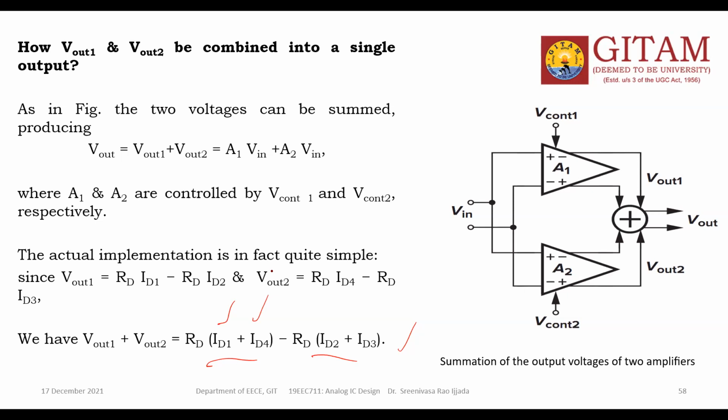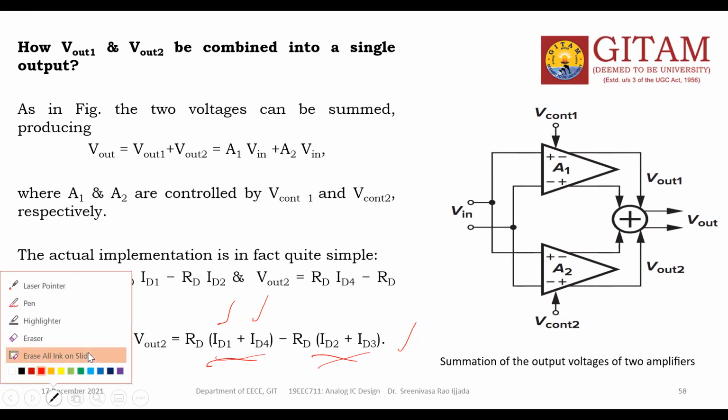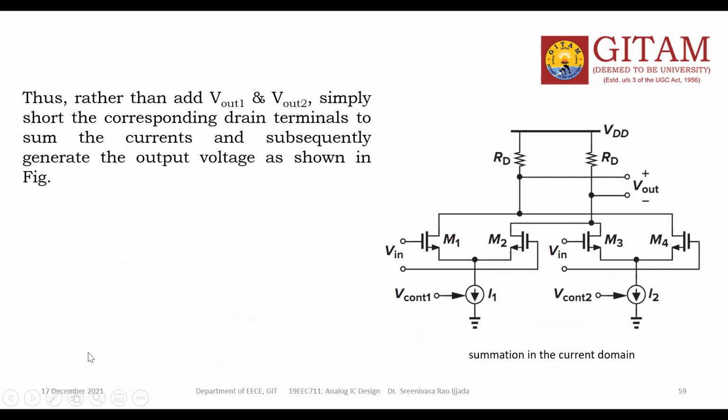So second transistor and third transistor, first transistor, fourth transistor, because they both are doing the same thing, so that you can combine these two transistors. Combine means you can connect all the terminals. Here I am showing the picture. First and fourth are joined, second and third are joined, drains and sources are joined. Gates are different, of course. This is the gate Vin, and Vin is circuit. This is the circuit. Got my point?